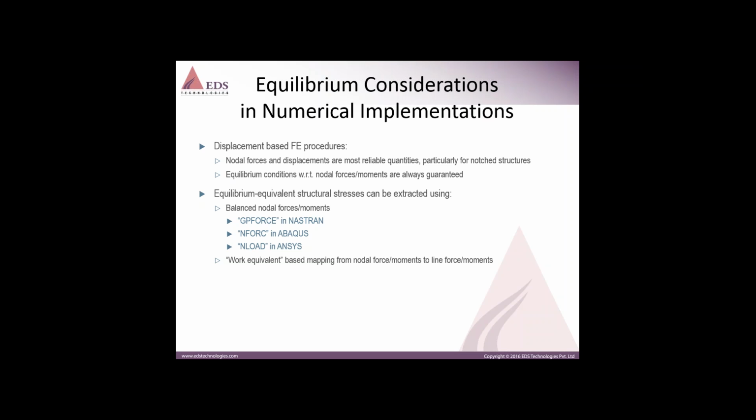That's what you want to be working with. The equilibrium equivalent structural stresses can then be extracted using nodal force in Abaqus and something similar in other tools. Then we apply a work equivalent based mapping to turn the nodal forces and moments into line forces and line moments.